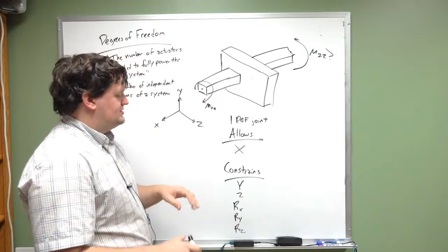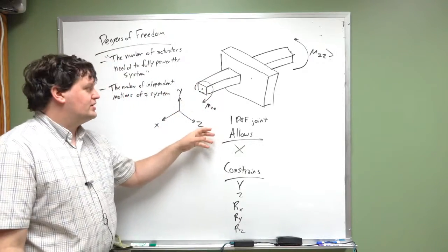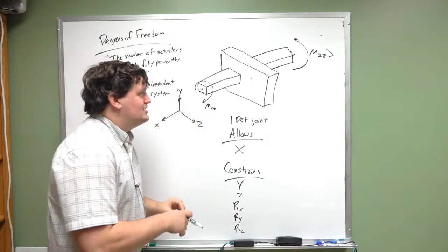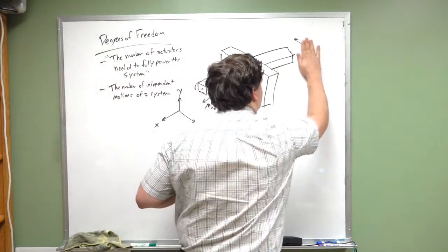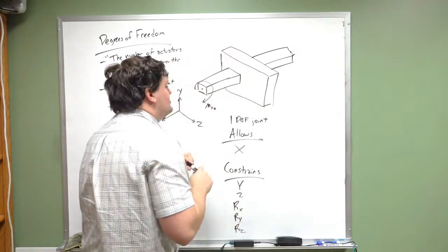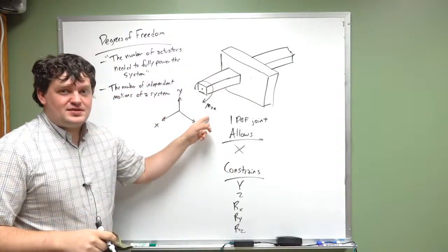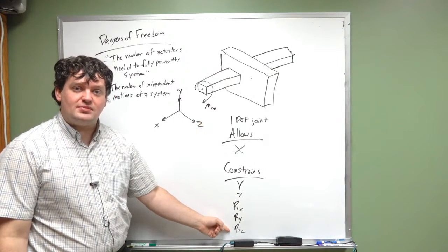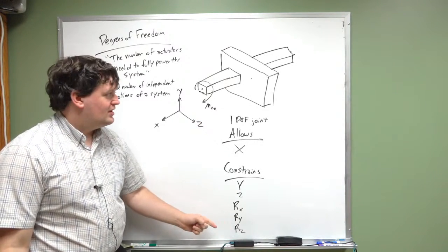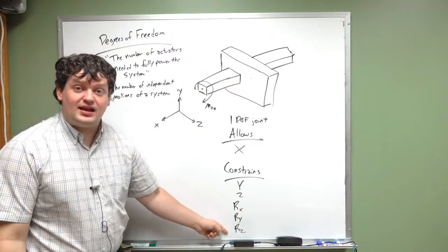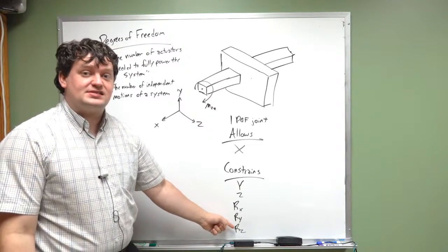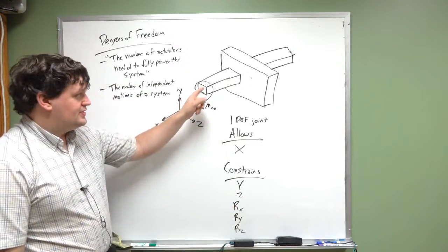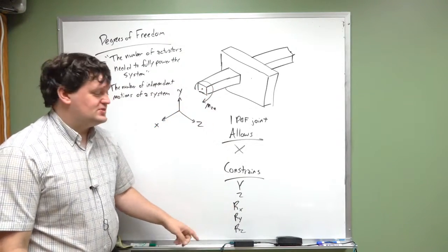I can't do any of this. So a 1 degree of freedom joint, if I were to apply a moment in the Z direction, the issue is I would need a Z directional moment here, because if you think about it, if it can't move and it can't rotate about the Z axis, then that means there cannot be any Z axis accelerations. The net moments on the system has to be equal to 0.